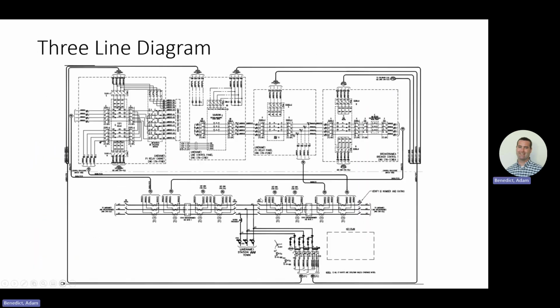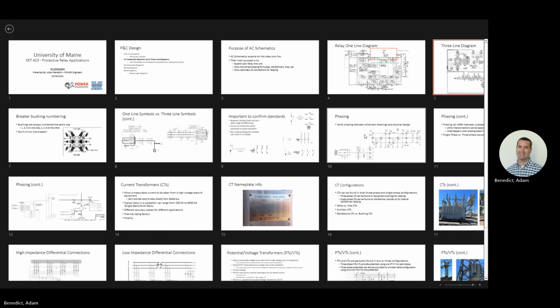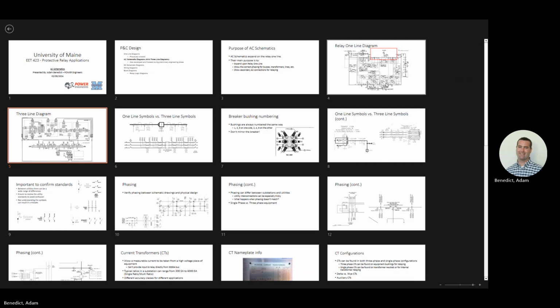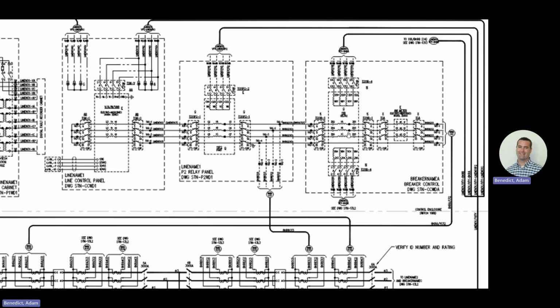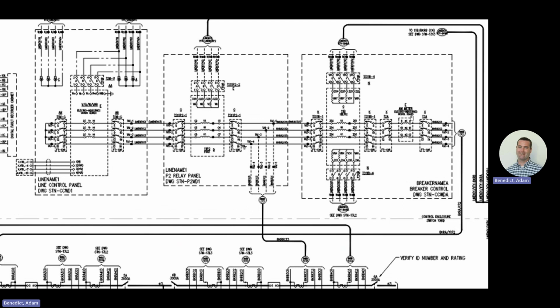We're going to take a look up here. So here you'll see this comes in, that comes in. Oh shoot, what happened? Okay. So here you have your CT come in to a meter, and then series on to, looks like your 11, so it'd be your breaker relay. So these are all in series. And here this reading comes in, and this is where they're paralleled in a sum.